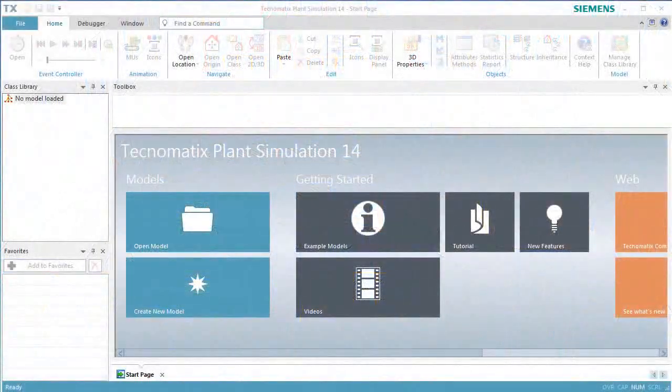This video demonstrates how to modify the built-in transfer behavior of a material flow object with an exit control. This control overrides the built-in exit strategy, meaning that we ourselves have to make sure that the part moves to the station of our choice. The material flow object activates the control as soon as the part is ready to move on after being processed.